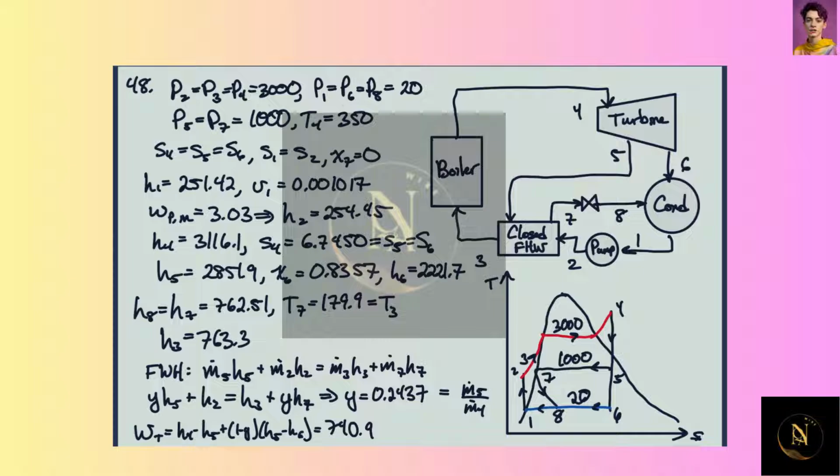No, actually, in this problem, I remember now, I drew this wrong. We are superheated here. So this point is actually outside. This curve should have come down more like this. So this is actually in the superheated region. But what we'll find out is if we keep dropping this pressure here, we get into the two-phase region. And in fact, we wind up needing to do the two-phase analysis at 0.5 to find the optimal, because it turns out that it's actually quite low.